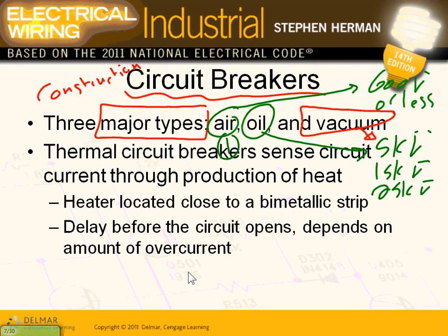Who cares? Over time, you will destroy your contacts. They will no longer work. And the higher the voltage, the more severe the arc is. So what they do is, in a vacuum, for the most part not completely empty, if you don't have air, what are you going to ionize? There's nothing. It's vacuum. So you ionize nothing. So basically, you can extinguish the arc faster. There will be no arc or a very small amount of arc coming out of the interruption.